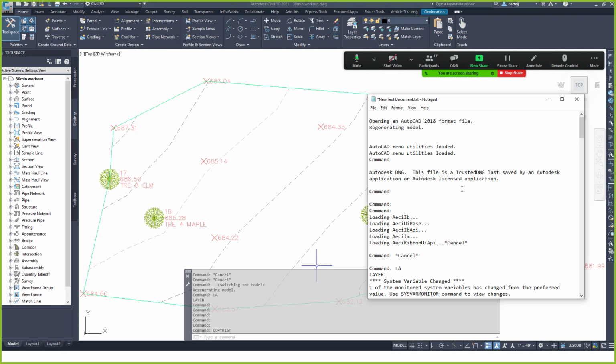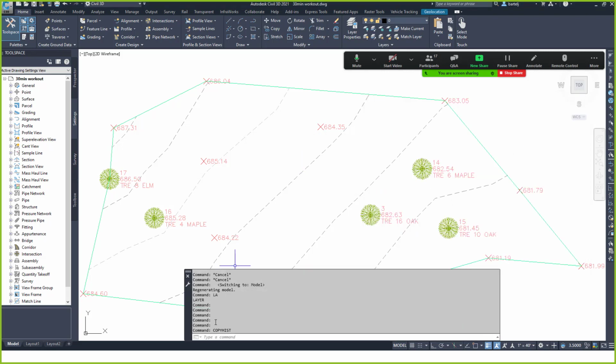But another thing, in the instance that we've got a problem, if we have a drawing, something fails, or we have a crash or something like that, and we're trying to beta test that or work with support to get something resolved, it's like, well, what were the last 5 things that I was doing that might have led up to having that problem? Well, if I'm out of the system, I can't do copy history, but there is something that I can do to help facilitate that. There's a command called, we'll say, log file on.